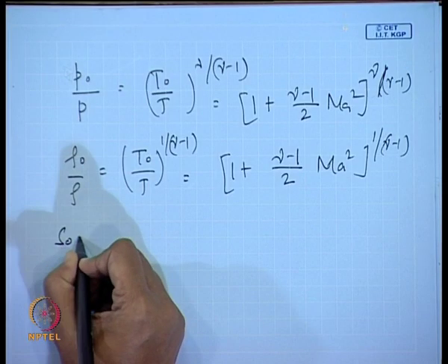So, it is not so very impossible. The stagnation properties are varying throughout the flow, and therefore, how to find them, it is of no use. It is not that. For most of the cases we can assume isentropic conditions, and for that case the reservoir where the fluid is at rest, the properties of the fluid in that condition give you the stagnation properties. Agreed?